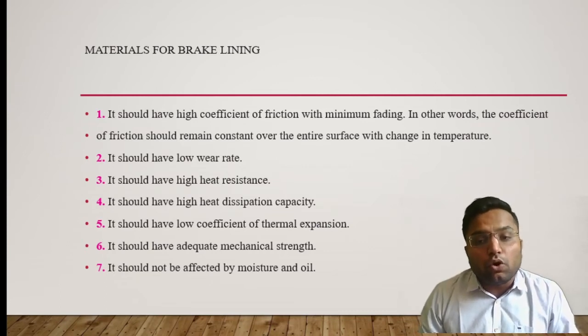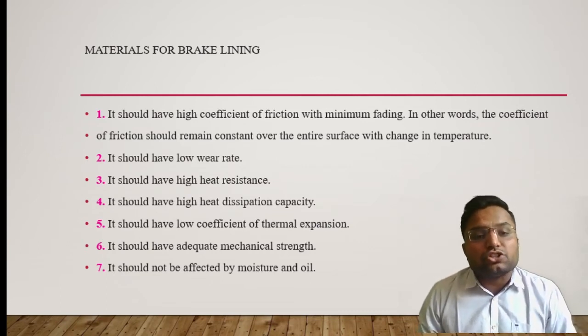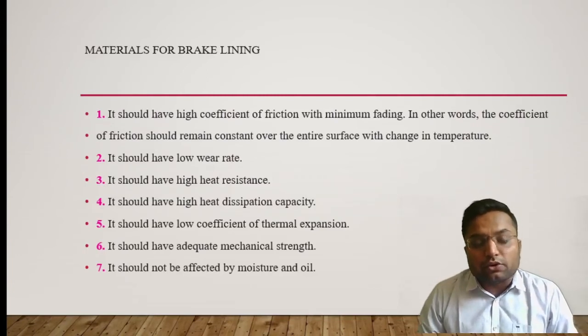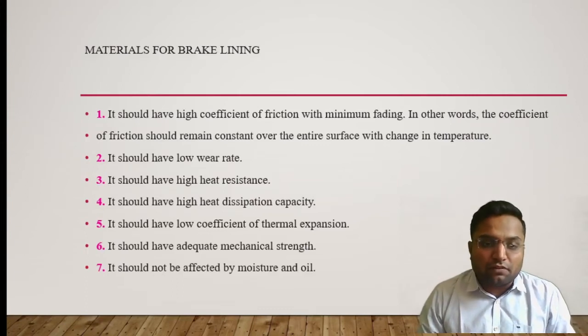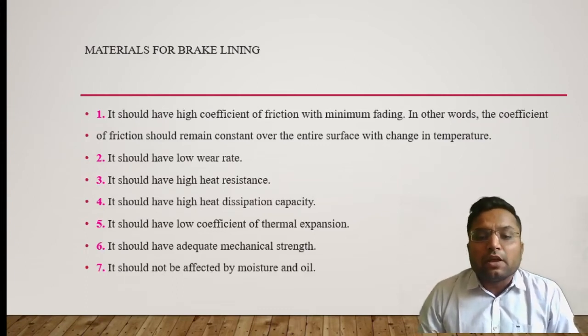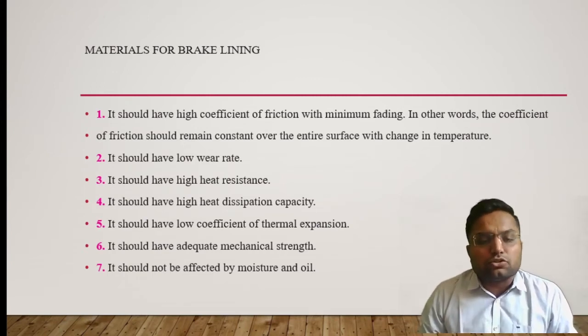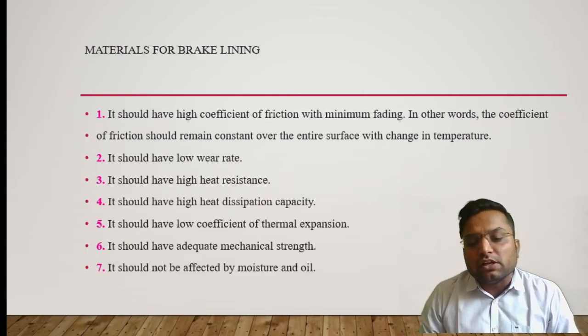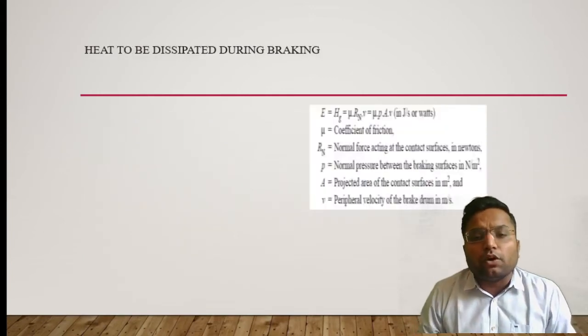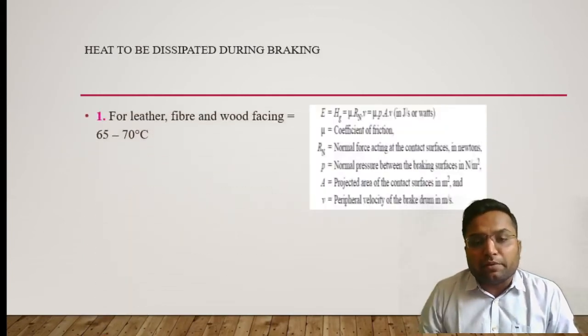It should show low thermal expansion. It shouldn't be changing its shape and size according to temperature changes. Clear? It should have adequate mechanical strength, toughness, ductility, wear strength, fatigue strength, anything. Clear? And it shouldn't be affected by moisture and oil. That's also a chemical reaction which comes under this case. Let's move on to heat to be dissipated by braking.